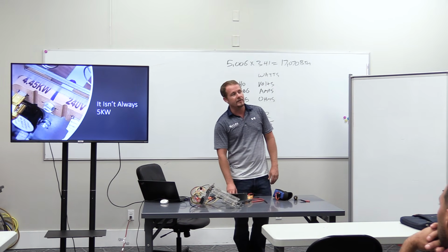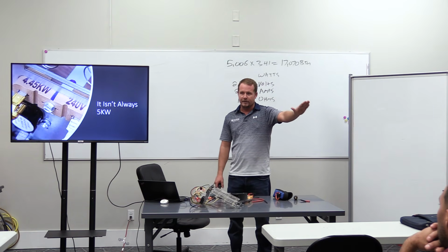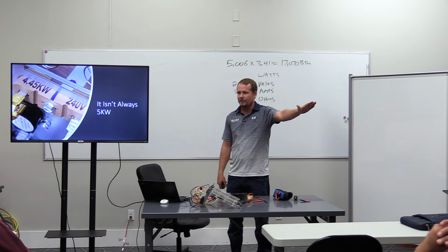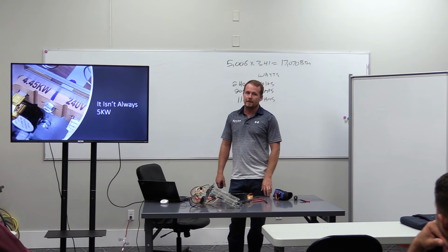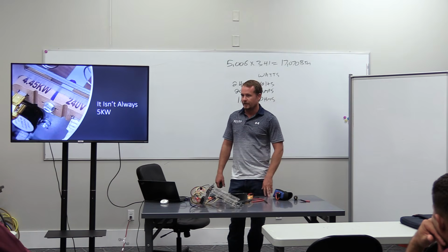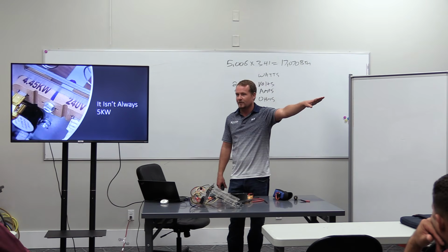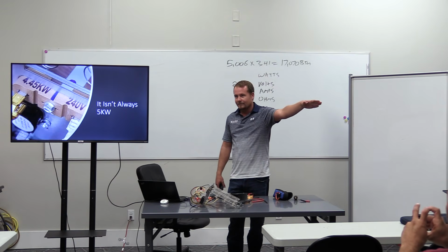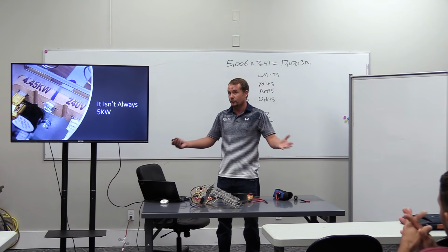It's just a silly thing that happens. When you look at what it tells you the breaker size should be, what the MCA is, is it telling you what we actually have here in Florida? No, it's telling you 230. What do we actually have in Florida most commonly? What voltage do you typically see in houses? 245, right? So what's going to happen to your current on a heat strip that's running 245 when the data tag says 230? It's going to run higher current, which means what? Is that data tag valid now in terms of what size wire it tells you to put on it? The answer is yes, it is, because it's what we got. But it's kind of a goofy thing that manufacturers do. Sometimes they're going to give you 230, sometimes they're going to give you 240, but even 240 isn't enough.